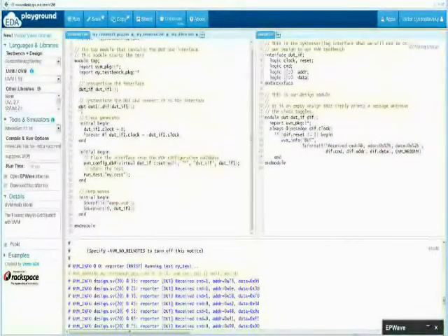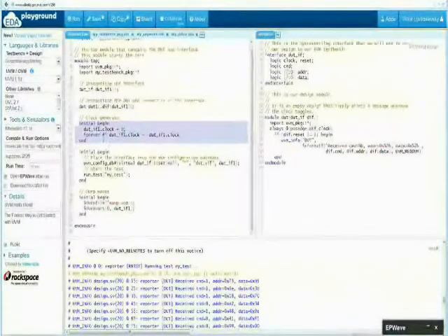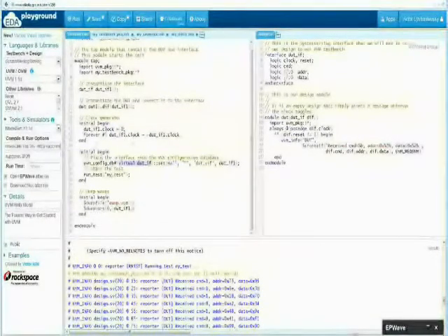On this software verification model, interface design under test, we use the interface to drive the clock directly from the top level. The virtual interface comes into play, and the virtual interface takes a pointer and puts it into the UVM config database.